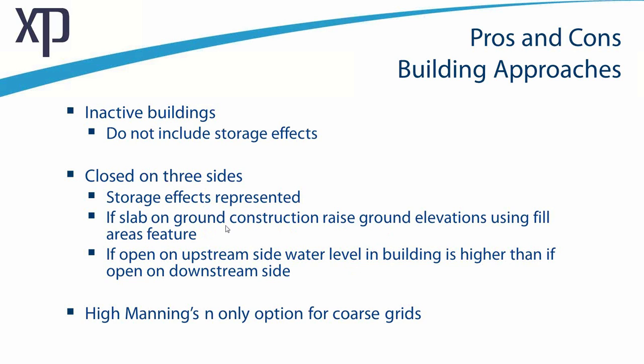Of course, as I mentioned, you can raise the building if it's slab on ground construction. You can raise the ground elevations, and that house or building will not flood until that water depth has reached the amount that you've raised it. And most important is that your storage effects are represented in this scenario.